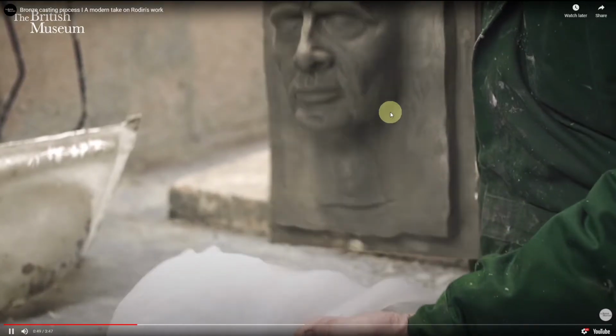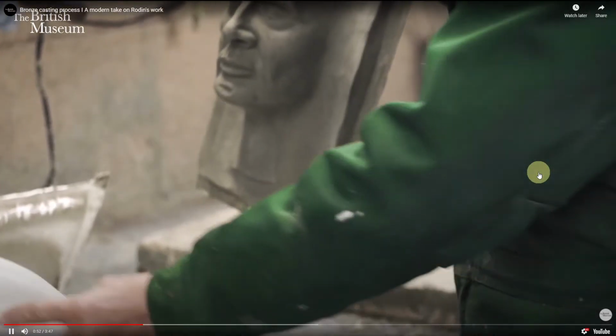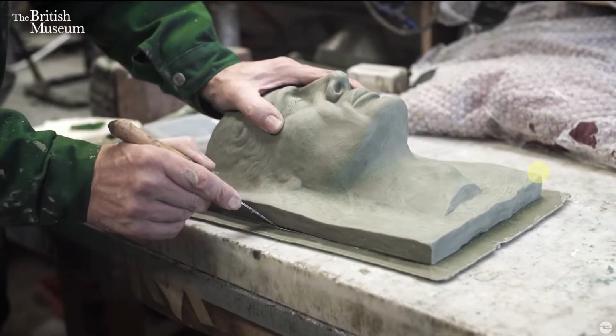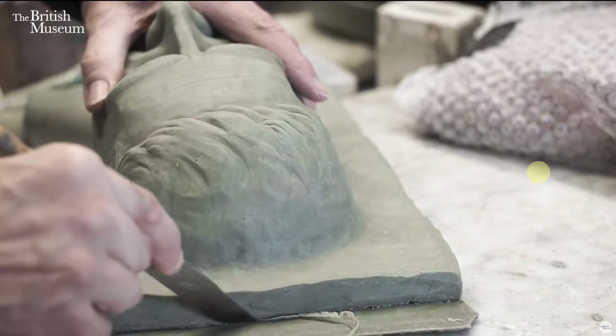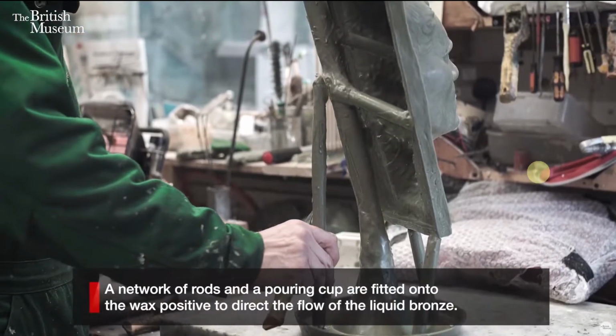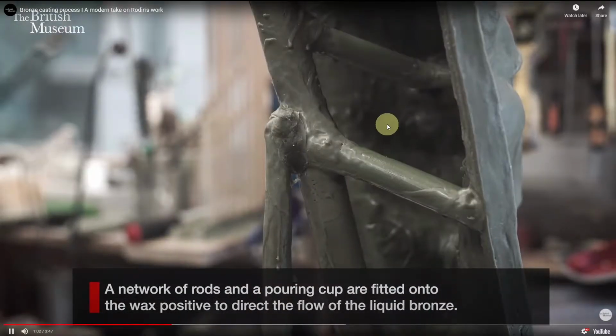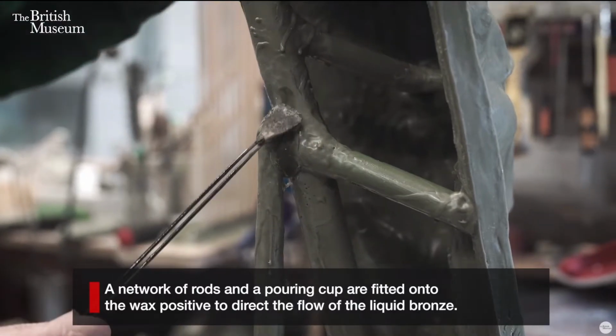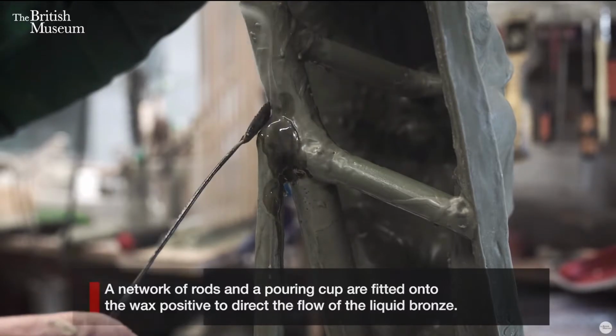So this is wax now. And you have to spend a lot of time on this rod system so that it doesn't trap any air or void. Otherwise you will have only a half-finished sculpture. So there's a lot of consideration and science behind this. Make sure that air escapes.